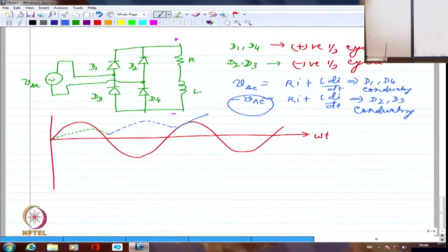That's why inductance works as a current filter, just like how capacitance acts like a voltage filter, because it gets charged and retains it. So higher inductance always produces a current where the ripple, or the difference between maximum and minimum, is brought down. So it evens out any oscillation in the current.